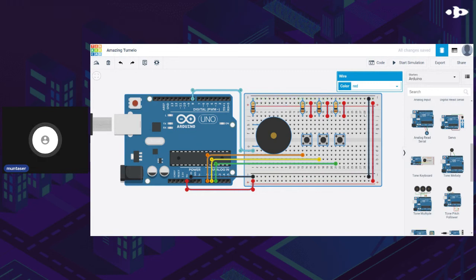Okay, then what happens is, in the middle, all these little columns of 6 holes, so 6, 6, 6, 6, like all these columns, they're all connected together. So anything that's connected to, let's say, this guy will be equivalent to it connecting to this guy and this guy and this guy and so forth.